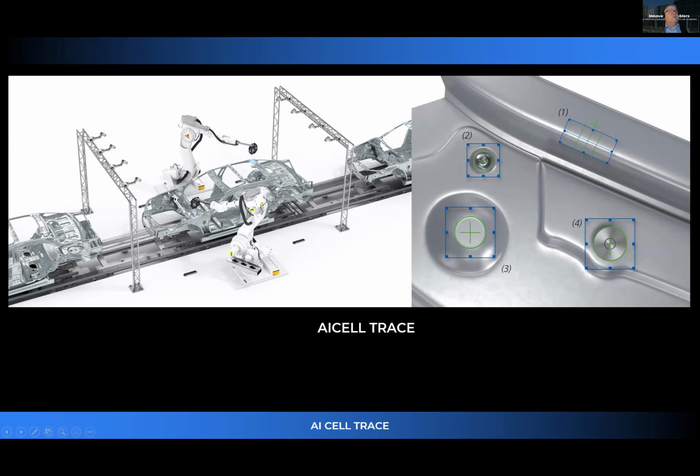and you're not worried about robot drift or robot correction, in that the camera system, which is all scalable to the size of parts that you need, whether it be a single component or a large vehicle, is tracking this as a tool. So there's really no relationship between the measurement system and the robot anymore. This is just a positioning device, and all of the metrology, the high accuracy, is between the relationship between the cameras and the end of tool. And that's what's calibrated. That's your traceable component.